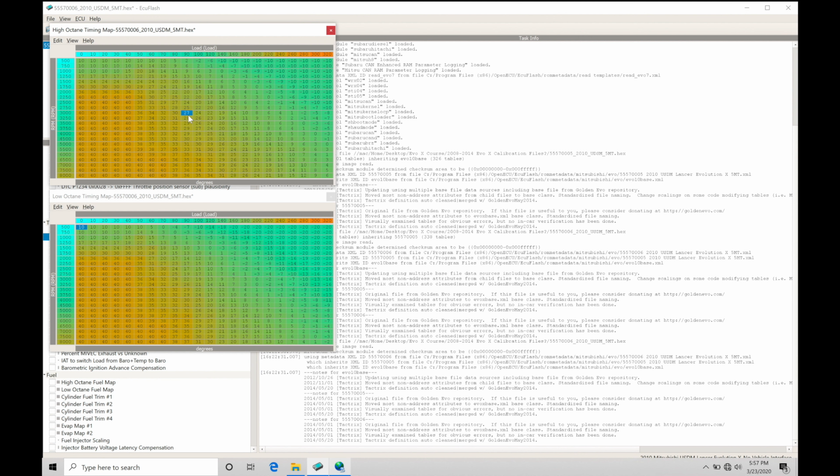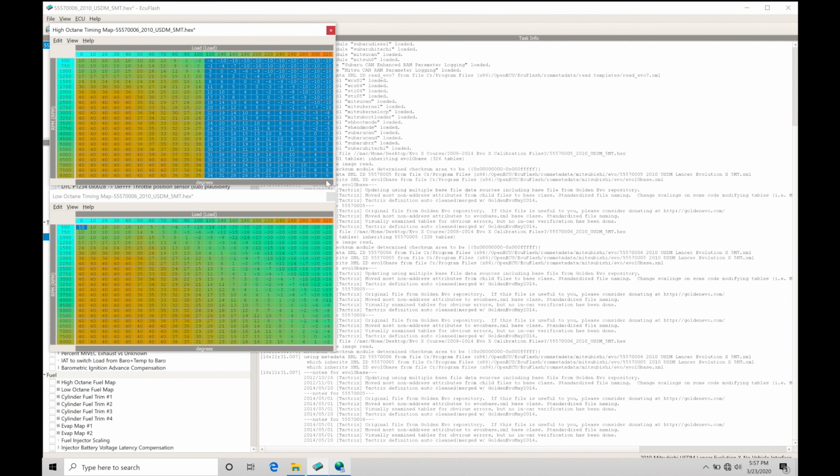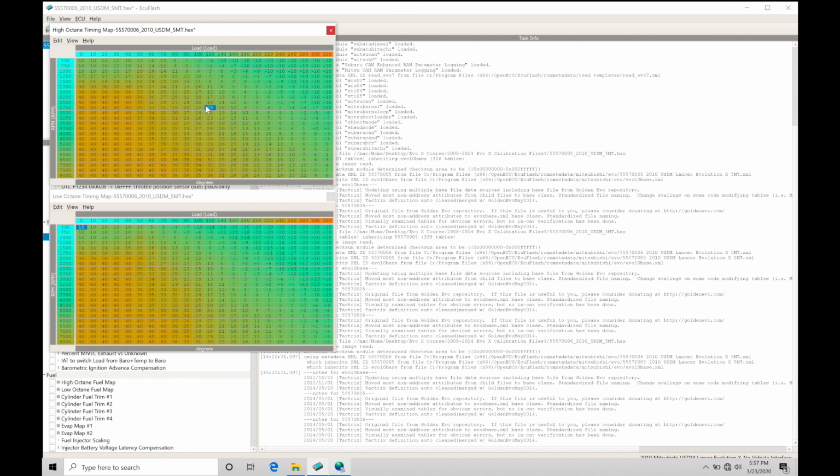Now, we're going to find that, just for reference sake here, 100 in the load should correspond to roughly 0 psi. From 0 to 90 here, that should be our vacuum area of operation. From 120 and above here in load, this should be boost pressure, positive manifold pressure. So as long as we've represented the math calculations and the MAP calculations properly, we'll find that the load here should be falling in line with what we just described there. That's when we know we have things sorted out, and it's going to be pretty accurate as far as our load calculation goes. That's one of the very most important things when we start to do our tuning process.